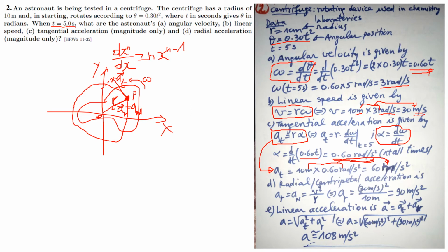Use a broken line. And let us find a parallel to AT starting from the tip of AR. The two vectors meet at this point. And then we need to plot a diagonal. This diagonal becomes the acceleration A. This is the total acceleration of such particle of the rigid body in rotation.